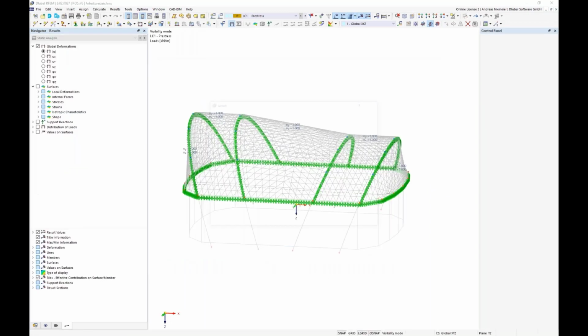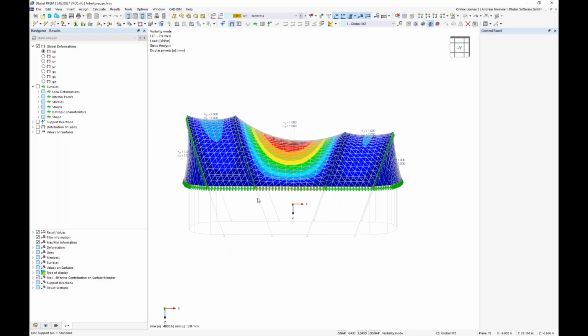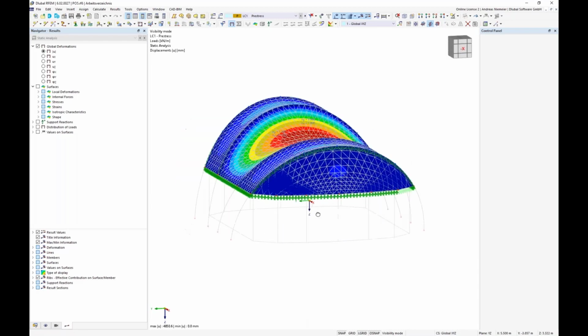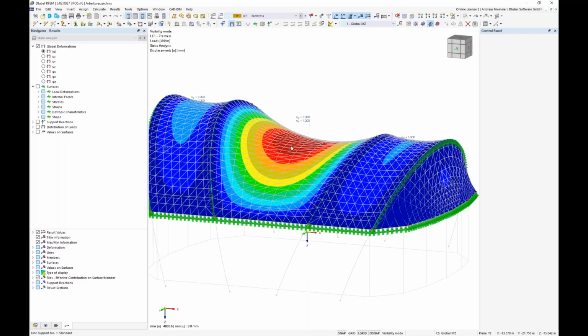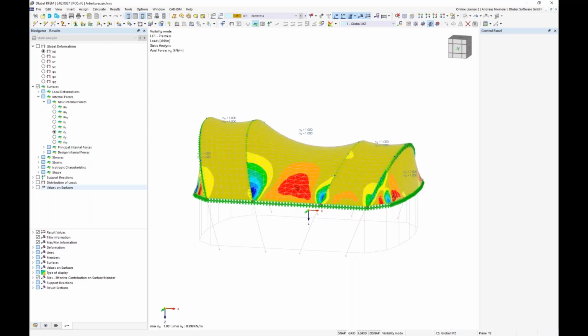And if you take a look now on the results, you will see that the program modified the shape of the surfaces a little bit. You see we have here a sag in all directions and even here in this direction, and this colored gradient shows us, let's say, the deflection from the original place to the new place. So far everything is nice. Even the surface holds the forces what we have defined here. For example, you see we are almost at 1, and even in the other direction it's almost 1.